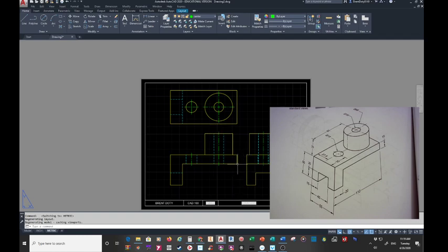The main thing that I want you to do is activate your viewport, which you can do by double clicking inside of here. To deactivate, double click outside the box somewhere, or down here where it says paper, you can activate where it says model. It turns into model, then you click on model and it deactivates. Okay, so when it says I'm in paper space, this is where you would have drawn your, see all this stuff here, you've got your fields, you've got your text, you've got your lines.